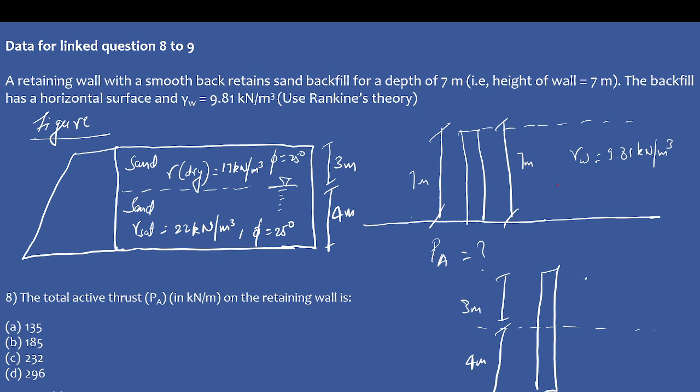First I need to calculate how much stress has been applied by the soil. So your stress diagram looks something like this, and then another stress diagram below this looks like this, and then you have the hydrostatic force, which looks like this.